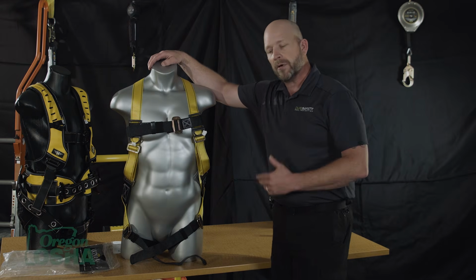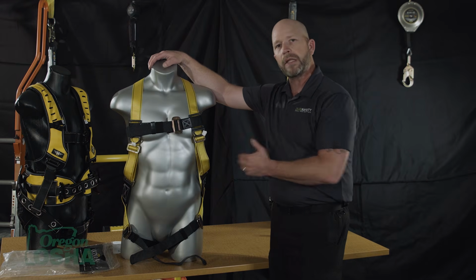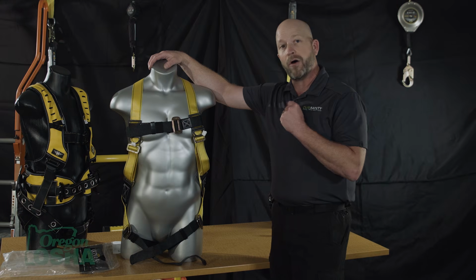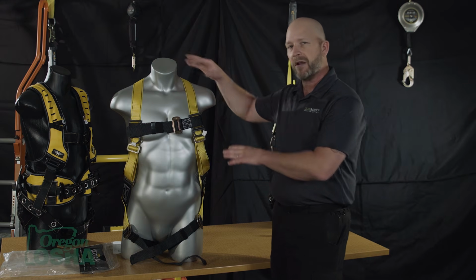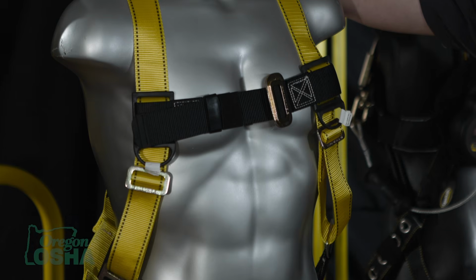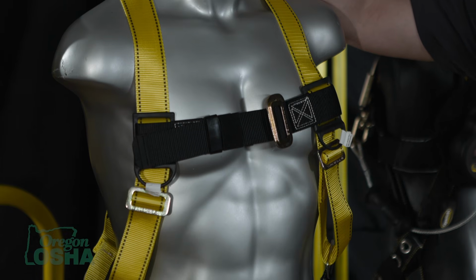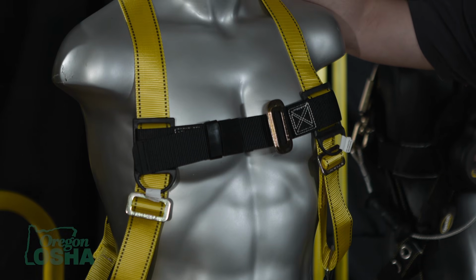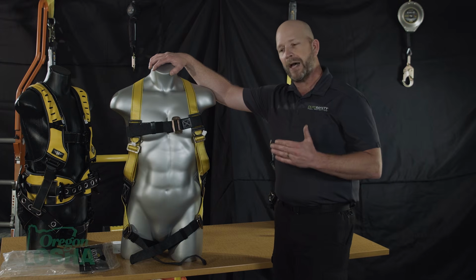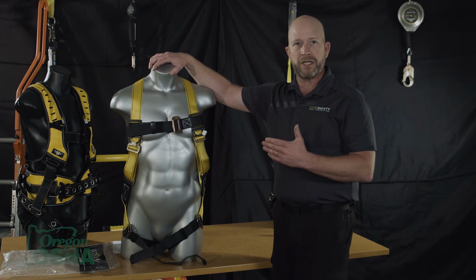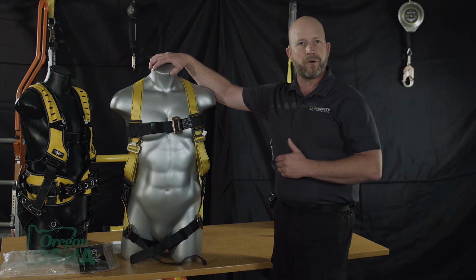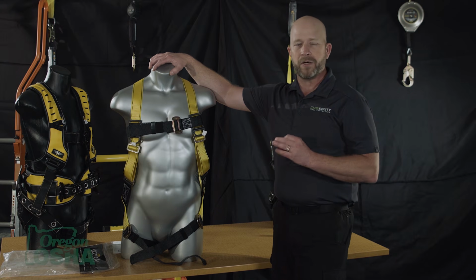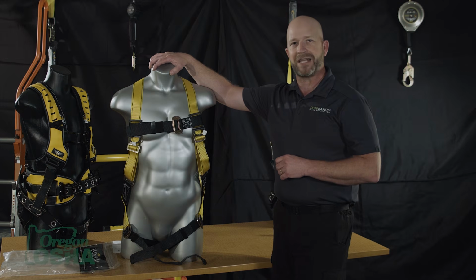One thing to remember, especially if you see a worker wearing the harness loosely, is that in a fall, we are accelerating. And OSHA is very specific about the amount of force that is allowed to be applied to the body in a fall arrest scenario. And that number is 1,800 pounds. And whether you actually do the mathematics, you're an engineer, or you're just a human being, 1,800 pounds of force, whether you've felt it before or not, one can assume can have some significant damaging effects to the human body.